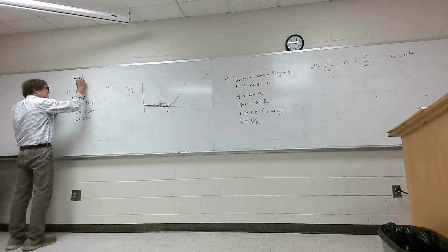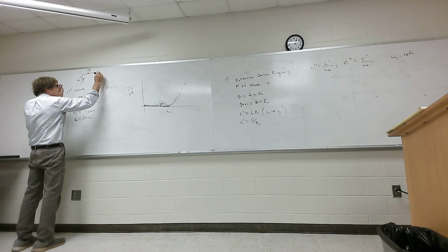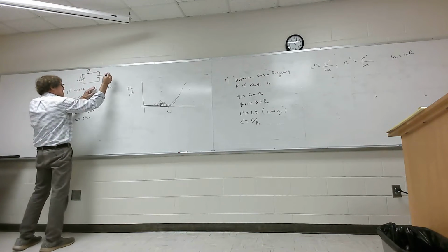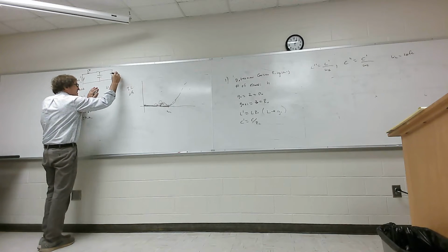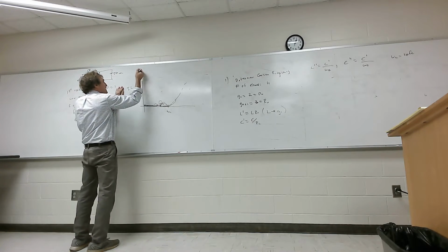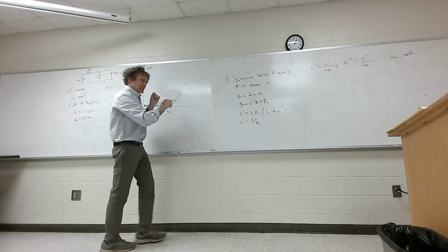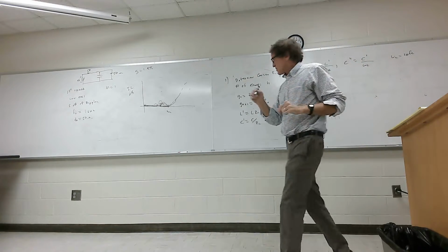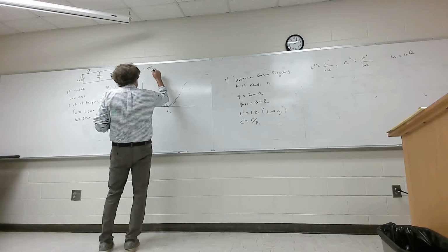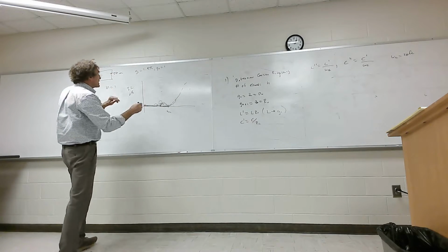But this is the source voltage. This is 50 ohms. And now this is going to be a capacitor. The value is second, and it comes over to 50 ohms here. So the first value I had is G1 is equal to 1.995, I believe. Yeah. And G2 is 1, which just means the load's 50 ohms. The only thing we care about is this.